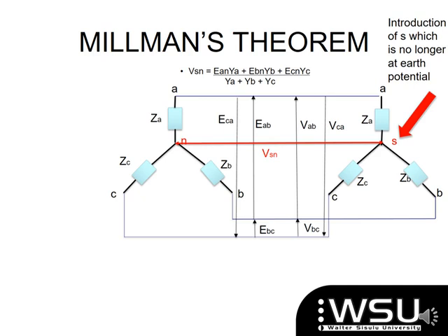You are given a voltage that is unfamiliar or foreign because your VBA is foreign, your VAC is foreign, and your VCB is a foreign voltage. So you were given those and you went ahead and drew those in with the ones that you know, and then went and did your EAN, EBN, and ECN. So obviously your angles were also incorrect there. So the first step is making sure that you get your voltages corrected.